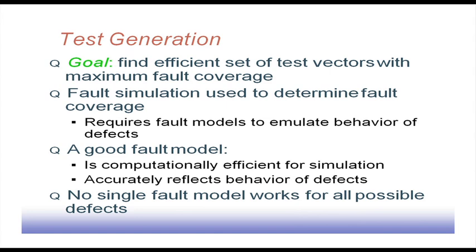So these fault models will be used. We will see what types of different fault models there can be, but a good fault model should be computationally efficient for simulation. It should not be very difficult to compute the values of different points in the circuit due to application of a test pattern under that particular fault model.